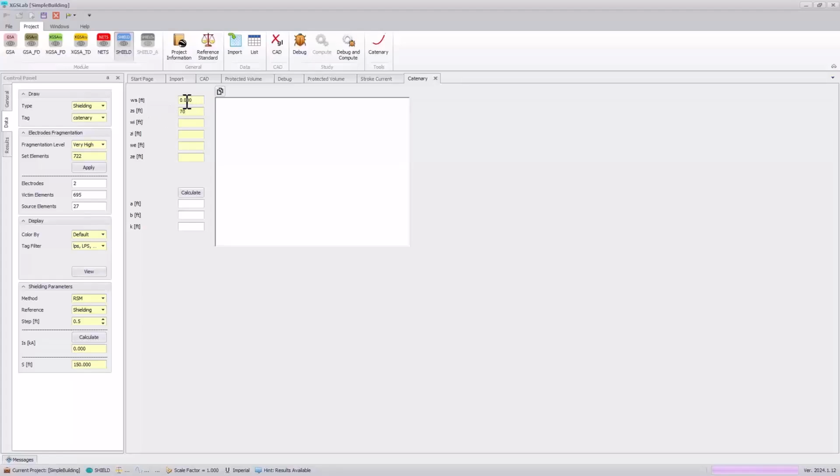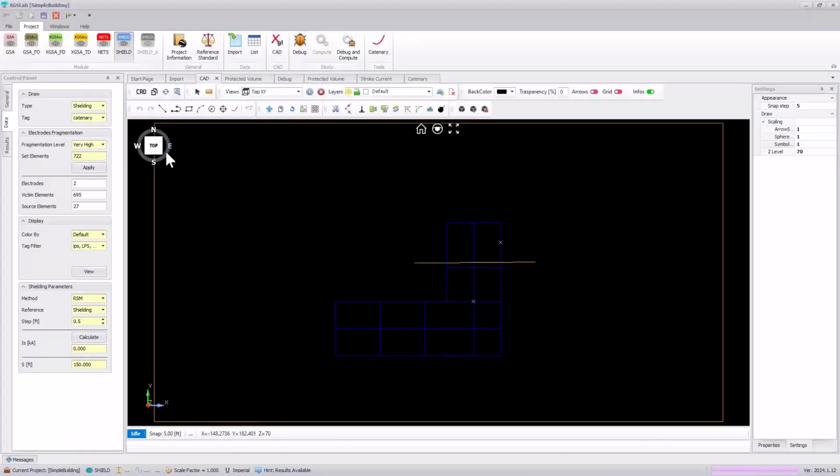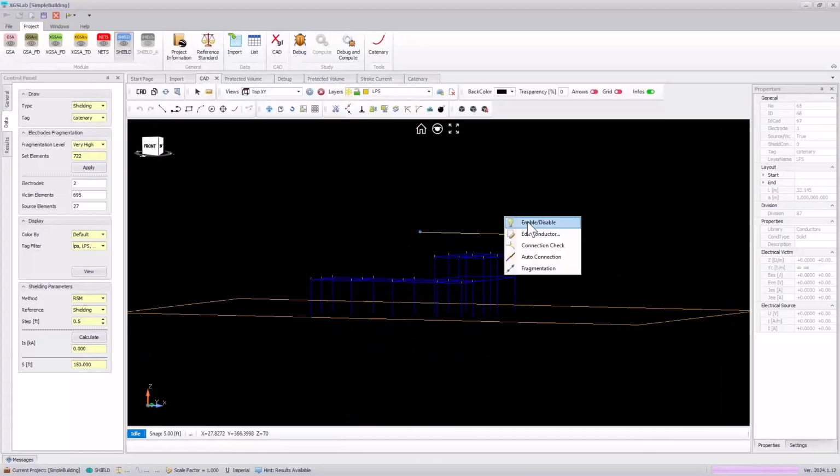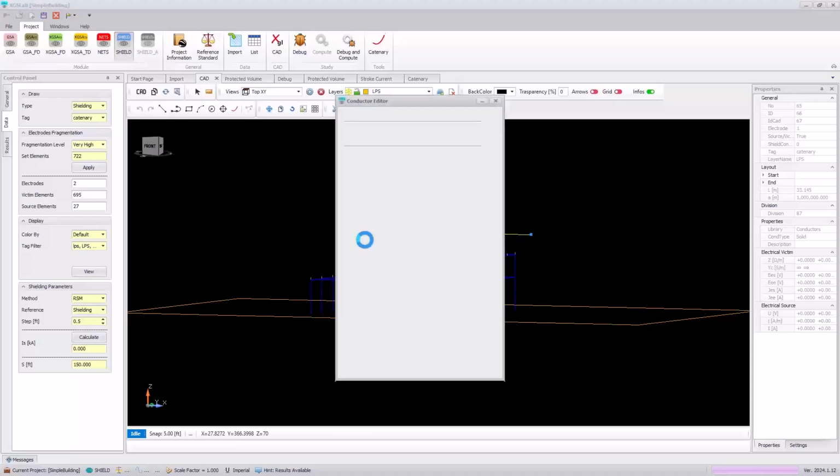So we have our starting point is 0, our elevation is 70 feet. Let's say at 50 feet, we drop down to 65 feet in elevation. And then we go to the end location, which is 100 feet. And then we have this ZE, where we're back up to 70 feet, where our masts are supporting that catenary wire. And this will calculate a parameter, a catenary constant. And then this is something that I can take into my model, and then I'll select this conductor, my shield wire.